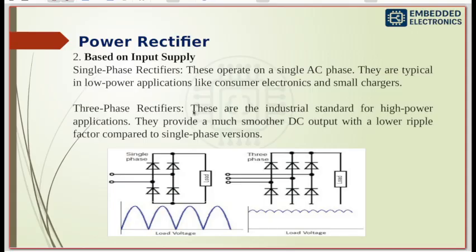So in the single phase rectifier, during the first half cycle, we know how the AC input is. During the first half cycle, electricity comes in from the top wire. Here you have it. Two diodes steer it, so it goes down to the load.